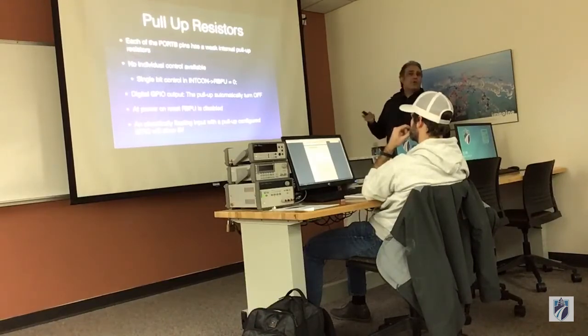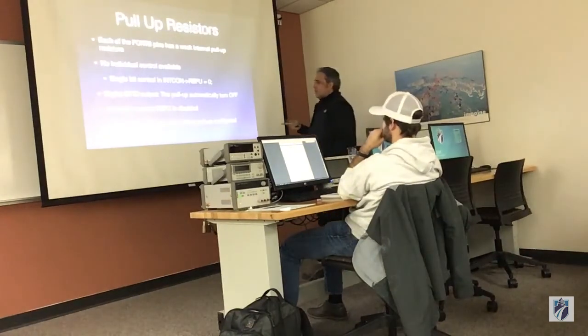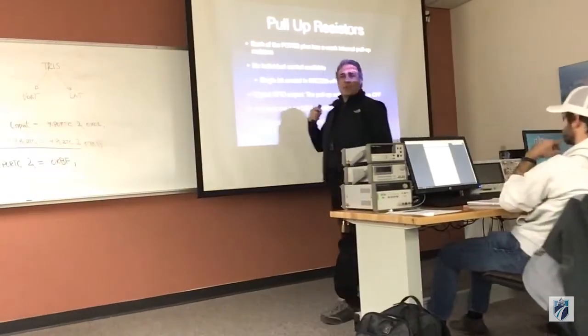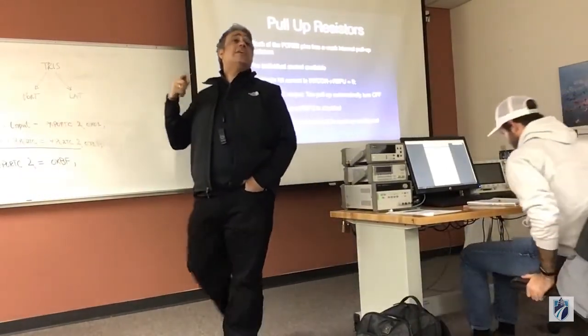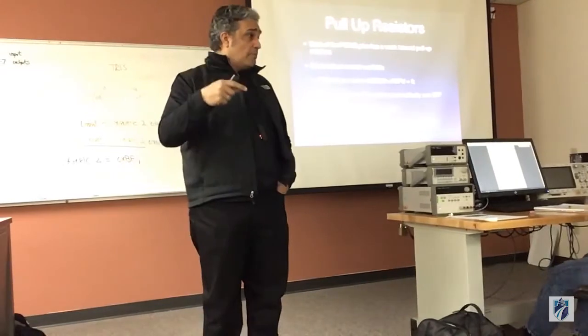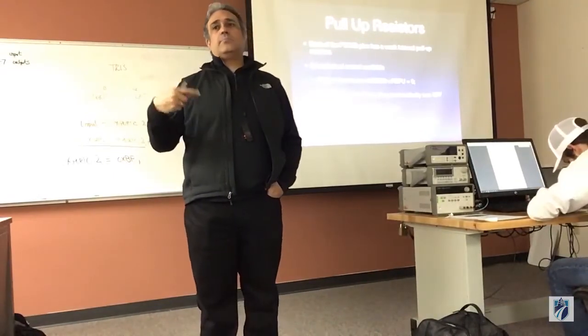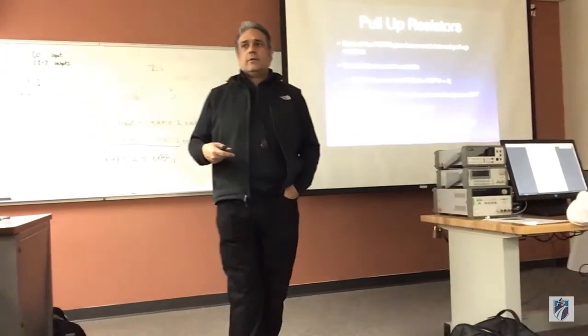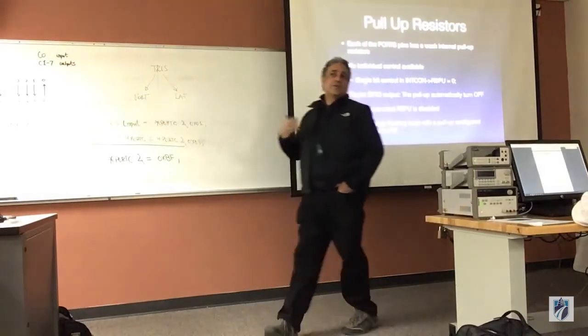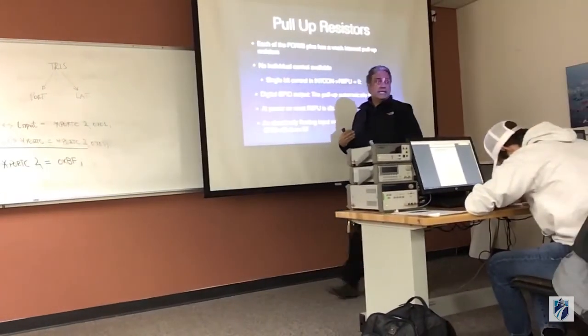Something interesting about port B, and I think this is very, very important for you to remember. Port B is the only port that contains internal pull-up resistors in it. All right, and these internal pull-up resistors are very useful when you're doing input interfacing.